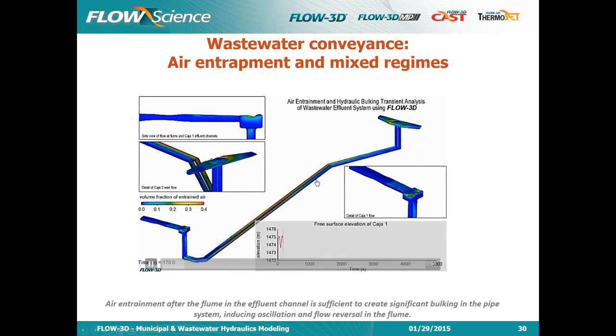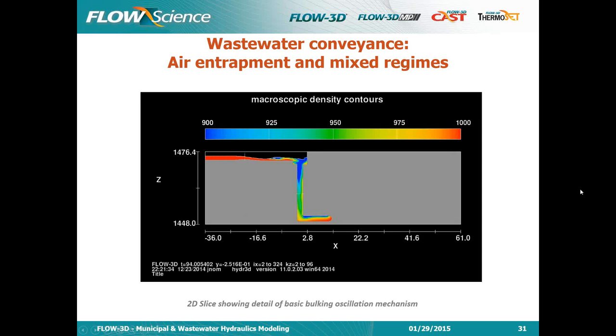It's kind of amazing actually when you think about it, but we ran the model and we observed exactly what was observed in real life, which is this oscillation in the tank here with the reverse flow onto the flume. The period here is actually about 80 seconds, very close to the 90 seconds that was observed, and then we have this pressure wave coming up on the outlet. So the whole system was modeled, and we observed exactly what was observed in real life. So this served as a basic validation for our model before we explored other remedial options.